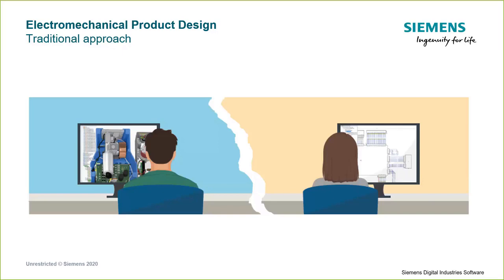more complicated if the electrical system software on the right-hand side is more of a drafting tool, and it doesn't have intelligence built into it. Changes are much slower. Any bill of material that needs to be generated from that has to be manually created, and that's very, very time consuming. So we want to change that, and that's really the opportunity. There is a better way to enable this communication as well as help with efficiencies by using the right application. Instead of using Visio and PowerPoint or something like that, let's use an intelligent wiring diagram application.